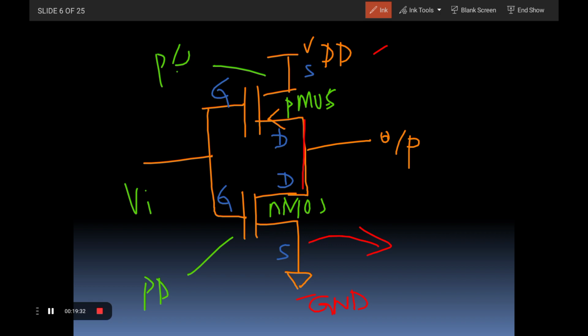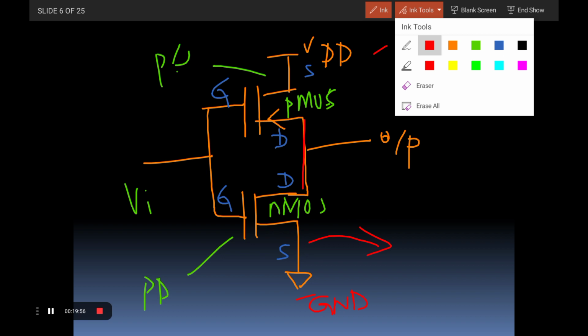The upper part is generally called the pMOS and the lower part is generally called the nMOS. The pMOS and nMOS networks are connected on the input side as well as the output side. The combination of gates is connected as the input, and the combination of drains is connected as the output section. Okay, let us see just one application of this, how it acts as an inverter, right? So for this case, let it be taken.